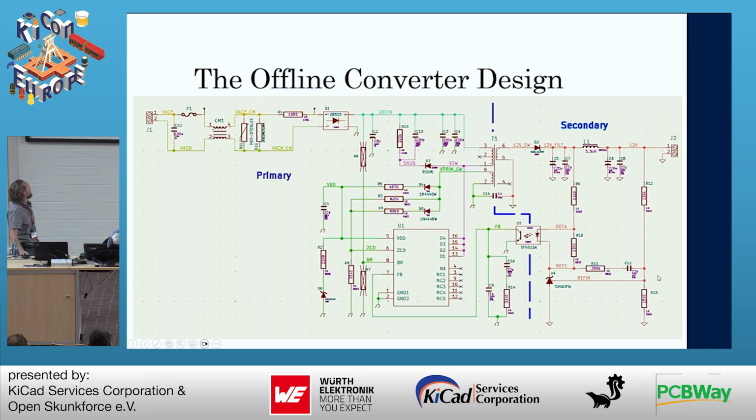And let's say we created a very large clearance as an isolation barrier and just said, okay, everything on the secondary side would have a huge clearance for those signals. Then they would also need a huge clearance to each other, which would make the secondary side huge. And you don't really want that, because there's no requirement for them to have a large clearance between each other. They can just use the generic minimum clearance that is common for your manufacturer, but you still want a large clearance to all the things on the primary side. And the same thing can kind of be said for some of the high voltage stuff.